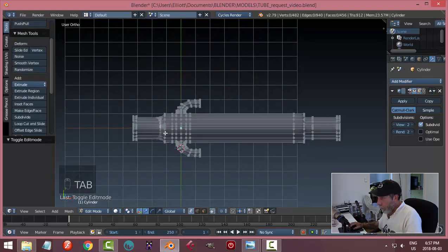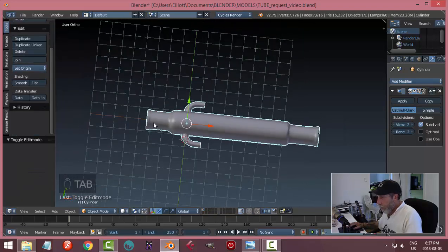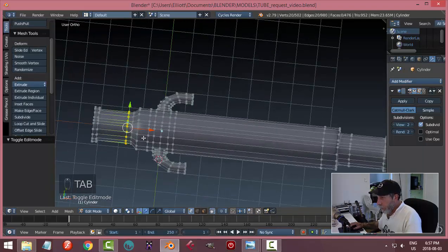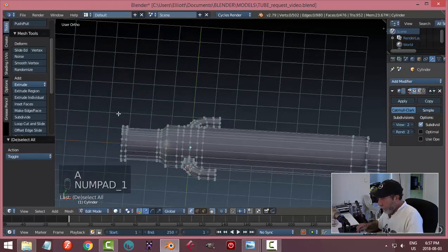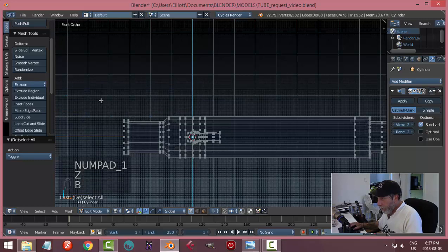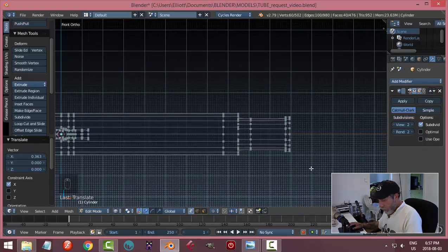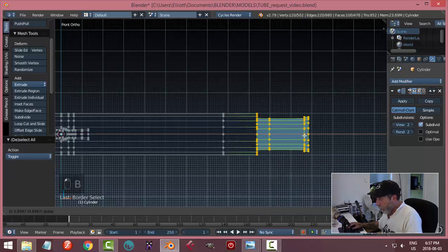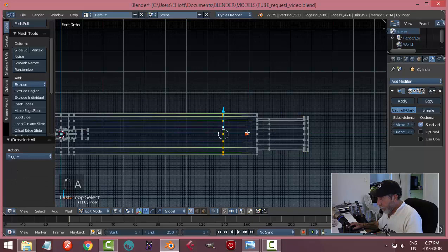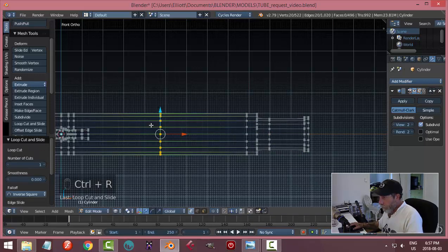Okay, now I'll sharpen up this one. I'll bring an edge loop in, bring it closer. And I have similar ends. I'll make this a little bit different. Let's bring that a little tighter. And let's, in wireframe mode, grab all of these and just bring them closer. And let's deselect that, and let's grab all of this and bring it down here. And Shift Alt click that edge and do that. I'm also going to put another edge layer just for support.